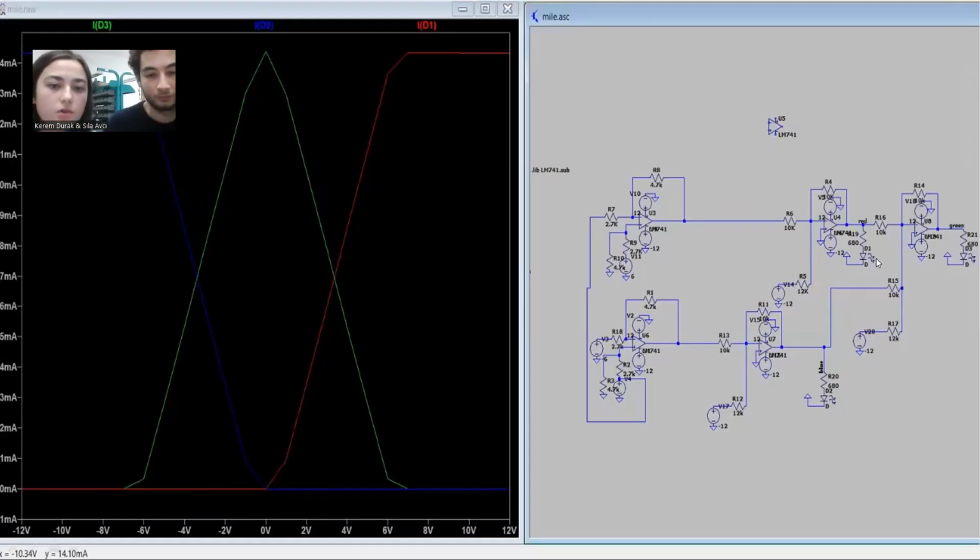So our design for the display unit focuses on analog control of the individual RGB LED currents, which allows for this continuous color change. We are using a combination of circuits which consists of different configurations of op-amps. The purpose is to translate the input voltage level, which represents the temperature, into the specific current mix for the red, green, and blue pins of the LED. So this ensures a smooth color transition, and this is what we will demonstrate in the milestone video.